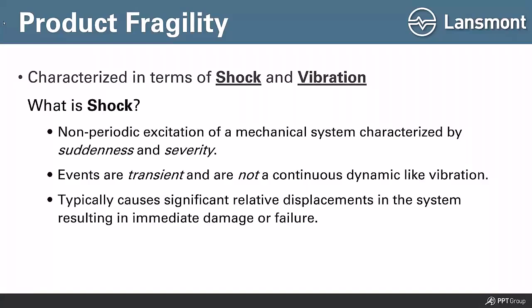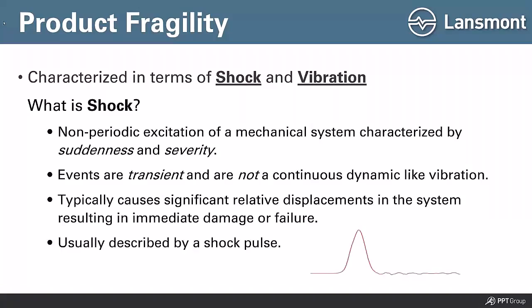And if we talk about damage associated with shock inputs, it typically causes significant displacements in the system, resulting in immediate damage or failure, thinking catastrophic failure. So it's not fatigue related. I take a big hit and I experience a big response, and that can be a catastrophic response. Something breaks, versus something wearing over time.